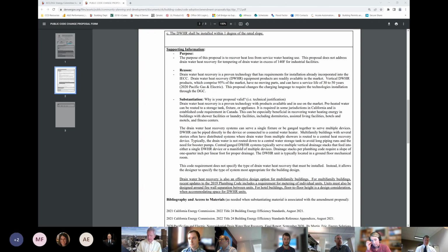So what I would suggest is that this is a good thing for the green code. These things are really pretty effective where applied appropriately. I would recommend that this stick with just the drain pipe heat recovery system. Now, how you could introduce wastewater heat recovery, heat pump heat recovery, is perhaps to make an exception. You would still meet the green code if you've done a centralized wastewater heat recovery system. And that is very difficult to try to explain and to write into a code. I'm not sure that that's practical other than as an exclusion or an exception to this otherwise requirement.